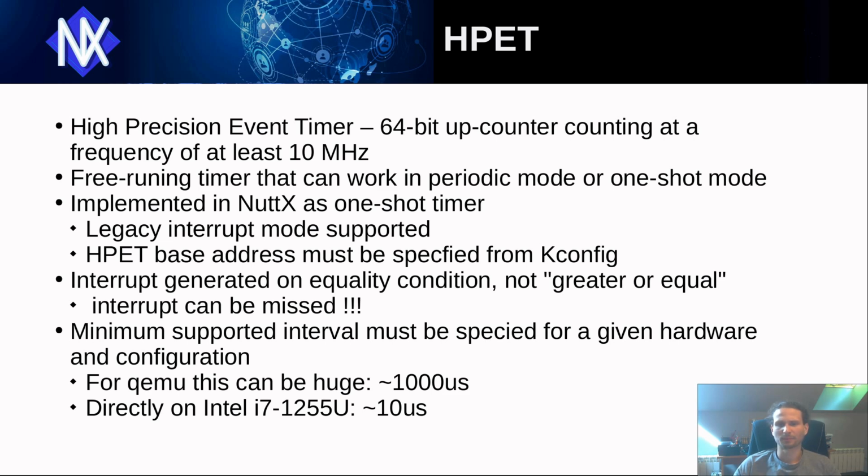HPET is a 64-bit up counter timer. It's a hardware timer located on the chipset, so access to it is over a memory area, unlike the TSC timer, which is an on-die timer on modern x64 processors, which can be accessed by CPU registers. In NuttX, HPET is implemented as a one-shot timer and works in one-shot mode with legacy interrupt support enabled.